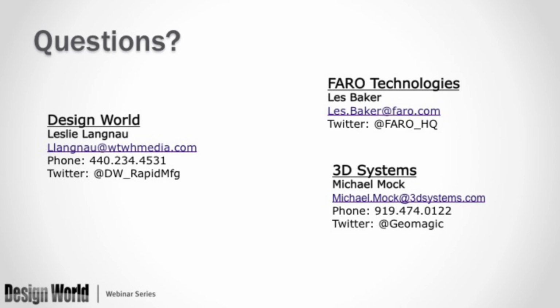Yeah, a machine that's set up to run a product like Pro E or Creo or SolidWorks or something like that will generally work very well for the type of scanning process that we're looking at today. In general, the scan data is very resource intensive, as Les mentioned, but we do as much as we can to try to reduce the burden on the machine, which is different than what would happen if you open the scan data directly into your CAD system. But a good graphics card is always good for any kind of 3D software, and the more memory you have, usually the merrier.